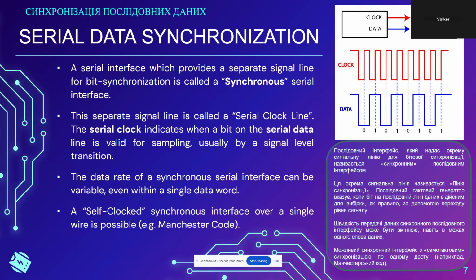receiver needs to be isolated. What the Manchester code does is it will turn a signal that is effectively a DC signal into an AC signal, which makes it easy to electrically isolate by using a transformer. That's just a little bit of history. The Manchester code was initially used in very early versions of Ethernet. I'm mentioning the name Manchester code without explaining exactly what it does. It's easy to look up. There is lots of information on Wikipedia if someone is interested.